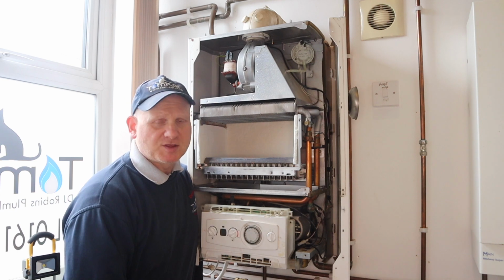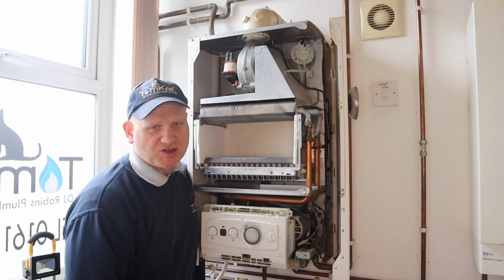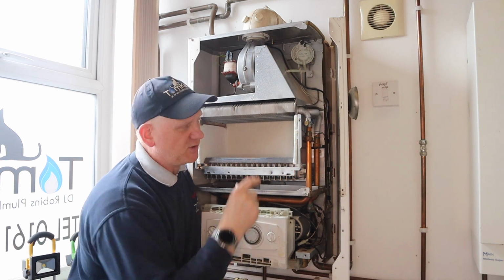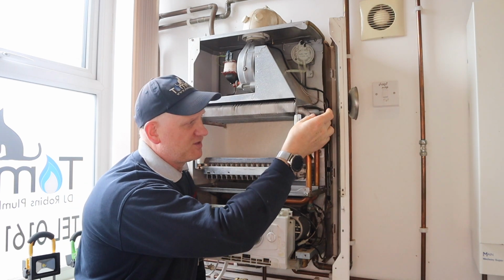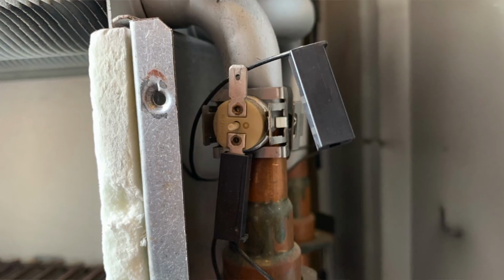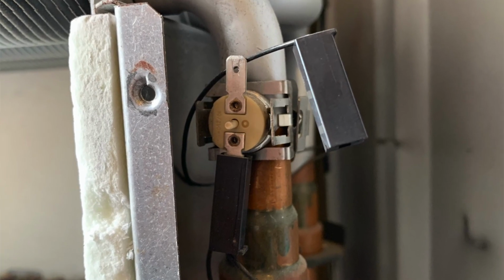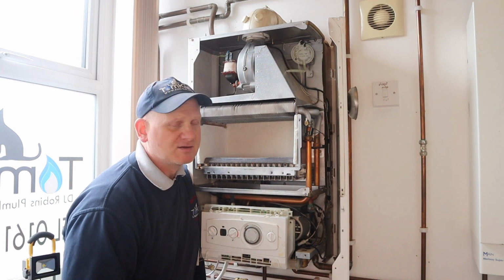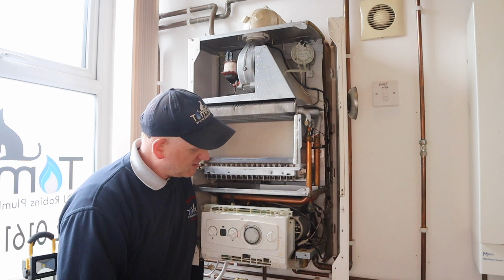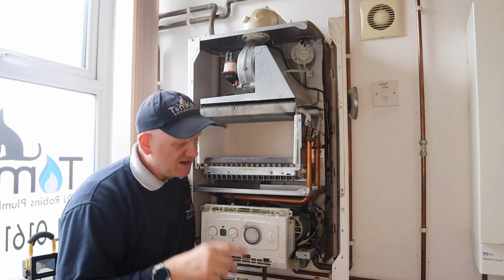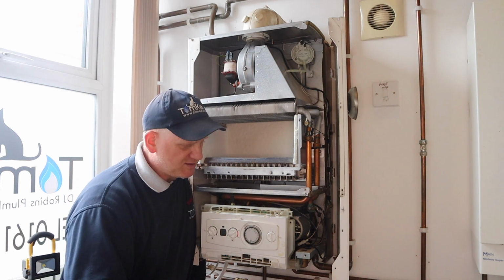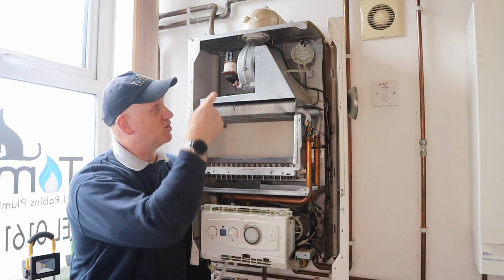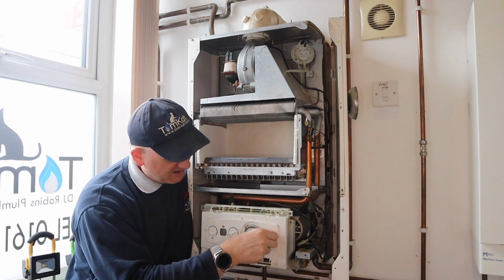Now this time I'm going to simulate that the over temperature stat has tripped. Now this has a manual reset button in the middle, but it hasn't tripped, so I've just disconnected one of the wires, because basically it's looking for continuity across these two wires to make sure it hasn't tripped, because when it trips it breaks that continuity. So let's turn it on. It should again go through its purge because I've put the fan back again.